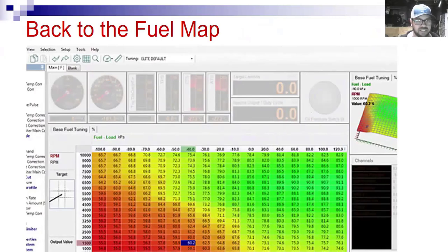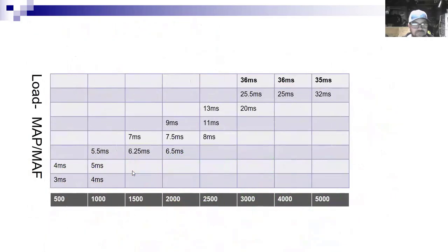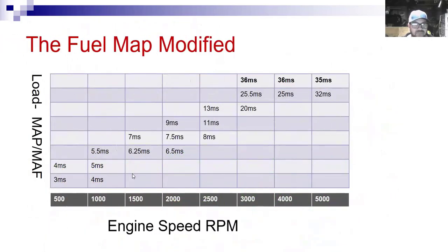So what you can see here is at lower throttle levels and loads, I have lower volumetric efficiency numbers. And where my volumetric efficiency numbers are the best is where I have moderate speeds and high load values there.